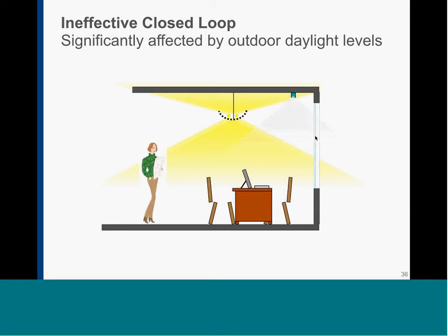Another case of misplacement is where a sensor is placed right above an indirect luminaire. These examples are not fictional. I have experienced them through the demonstrations that we have done, and this is how I figured out how bad they are. The photosensor is really saturated by the electric lighting, so now daylight becomes noise. That's why I recommended before, find a space that has a balanced light output from daylight and electric light, and point the sensor to that particular space. If you only have one sensor, as we will see, there are easier ways to eliminate this issue of placement, and I will talk to this the rest of this talk.